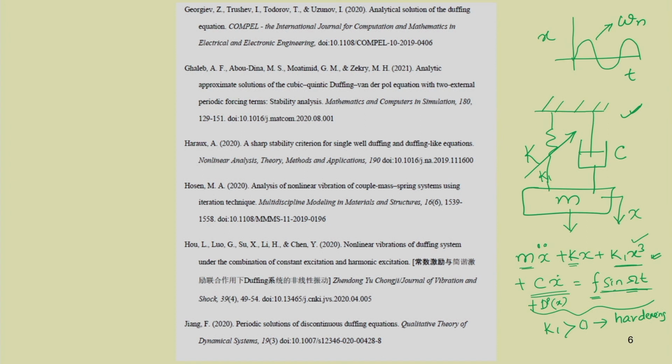Now, by adding damping, the system can be modeled as an underdamped, overdamped or critically damped system, and one can study the response of the system. For example, in an underdamped system, the response will be oscillatory. In a critically damped system, it will take minimum time to reach the equilibrium position. In an overdamped system, it may not reach that critical value, depending on the value of C.